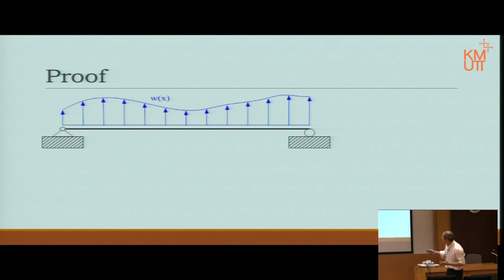Okay. Now, if we carry on, then we have a small cut. But as I said, we don't want to get involved with the support. So W apparently has to be 90 degrees, meaning if it's at an angle, then we only consider the 90 degree component. Now, if we look at a small distance on that beam, which we call dx at any position of x, notice that in this case, it actually doesn't involve the condition of support. It's a general proof, meaning in real practical examples or any problems, it could be any way you supported it.